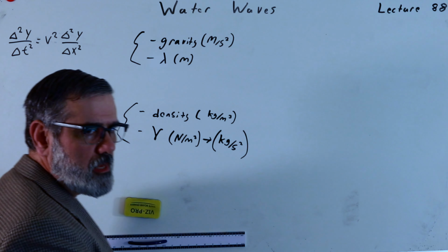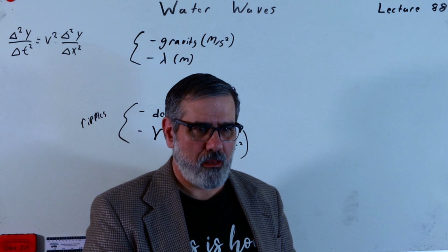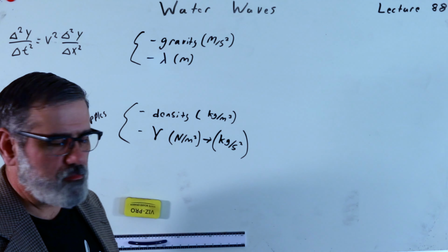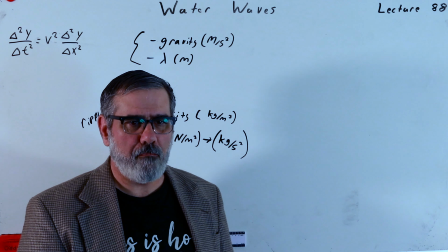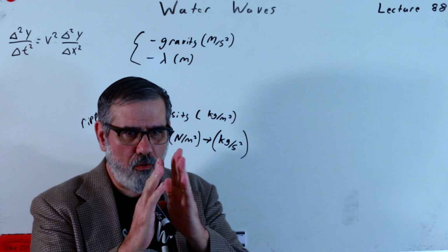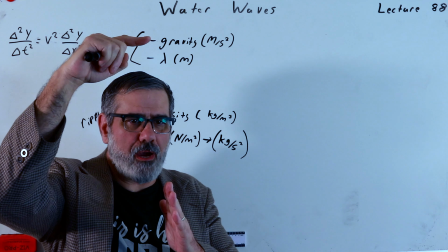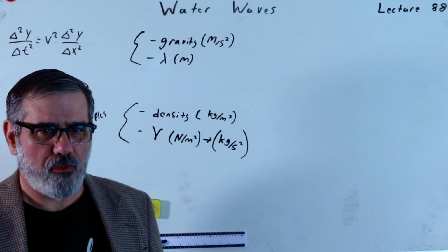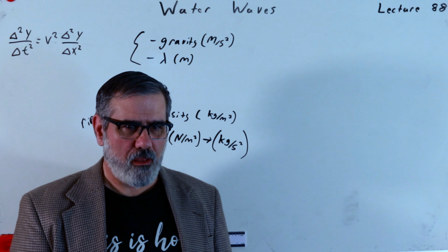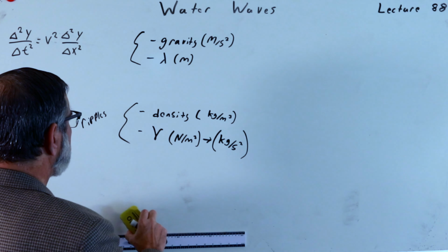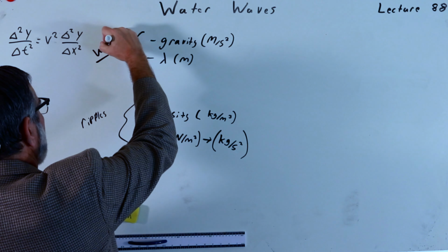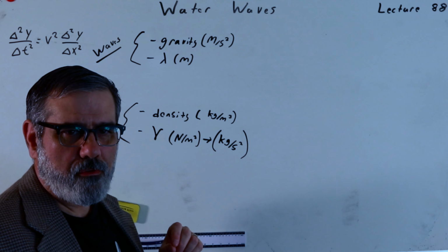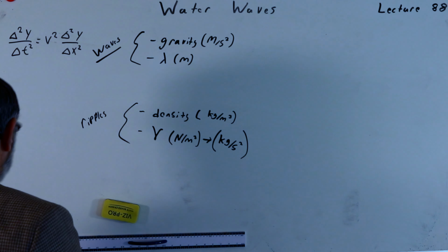These are really small waves, kind of like the things that you get when you drop a pebble in a pond. Because the amplitude is so small, and it's not being displaced very much gravitationally, it's not a huge mass, surface tension is playing a much stronger role there. Just like it is in the narrow-channeled tube, it allows the water to crawl up the pipe. There the surface tension is strong because the element of water is a small mass, so the gravity is weaker. And then this would be what we'd have for waves. So we'll have proper waves and little ripples, the two regimes we're going to look at. Let's do the ripples first.